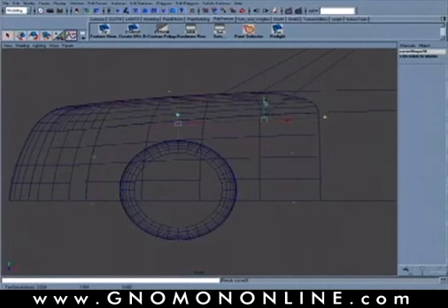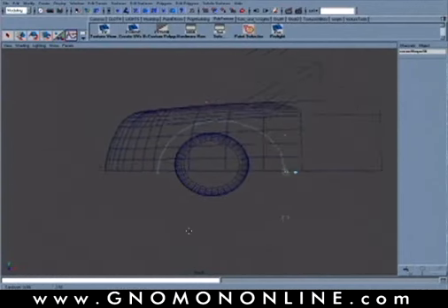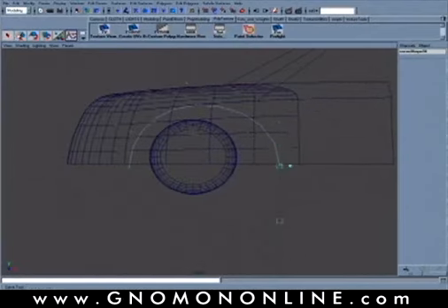Okay, you can also use this square manipulator that's off the curve editing tool and prop that back and forth to give it a rotate. Or again, coming back in and line this up at the end, so I can say line that to the x-axis, so that one's tagged in there. Okay, you can also scale from this point. So if you use the scale slider, you can pull this up a little bit higher, again on just how you want to design that overall wheel arch.